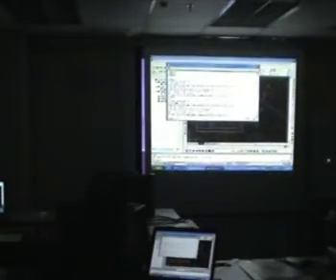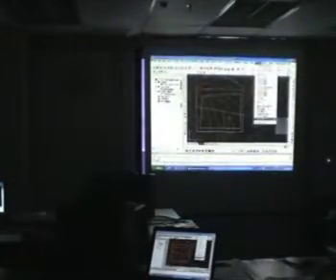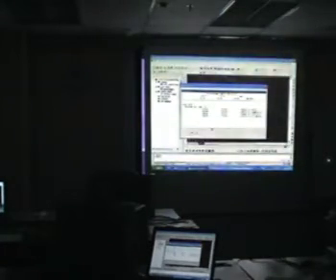So of course, looking at it in your text window history and writing this down is very troublesome. So what you can do is compile a summary report. You start the report. This is where you can again do any correction factor adjustments if you need to. If it's a 1.2, you can put 1.25 or 1.5, you can set them here. We're just going to leave this as is, hit OK, and this is the summary.